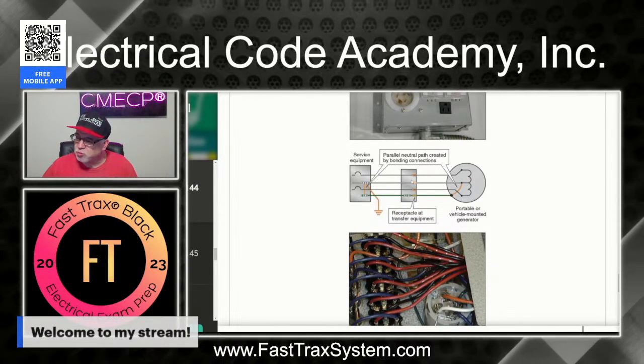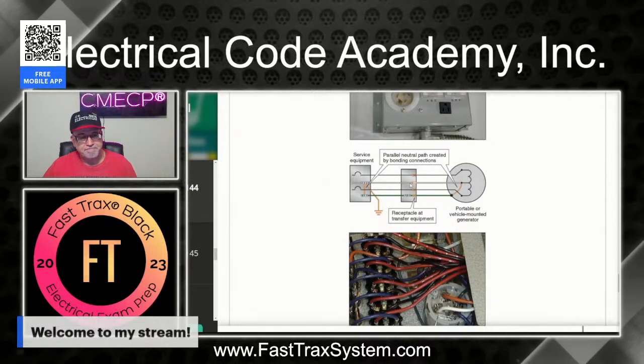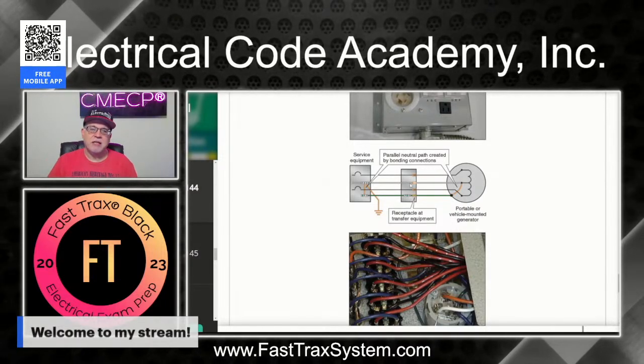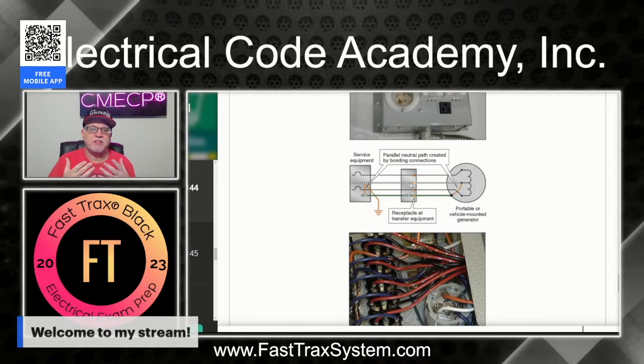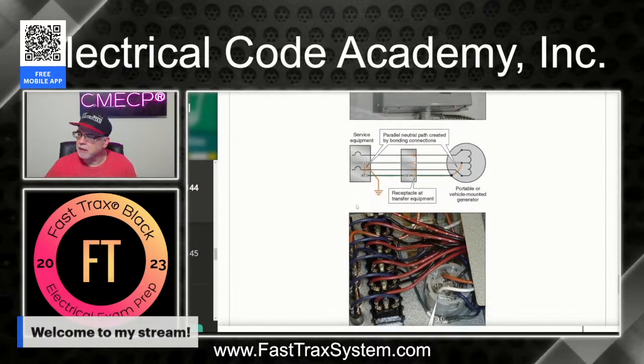You need to switch the neutral. And the sad thing is, when you're buying transfer equipment, it doesn't necessarily always come with the generator. So you've got to be careful what you buy. You've got to know what you're buying. And again, you can create a serious issue if you don't know what you're buying. Okay.